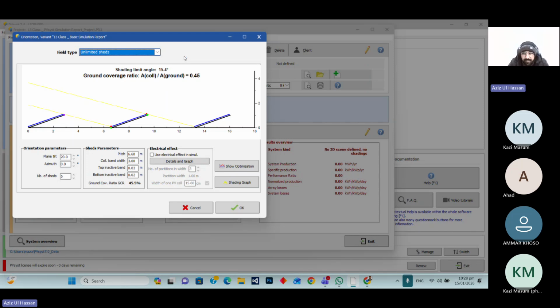But here, where I have selected the location, we are installing just a simple ground mounted system. We have a pitch of 10 meters and a tilt angle of 25 degrees. So we select that option, 25-degree tilt angle and azimuth zero. Shed should be like 10 or 15, just random options available.